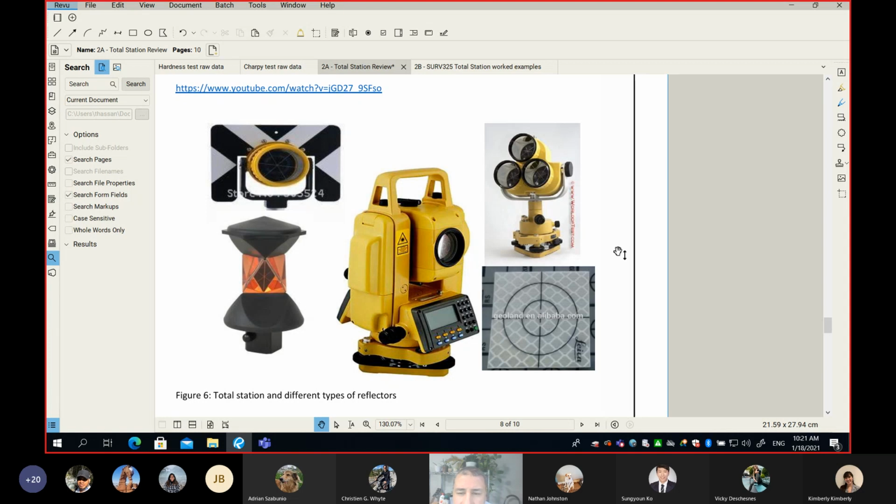Can I get some help, please? I'm asking you, do you think I'm going to, for example, I want to find the coordinates of a manhole or a building corner or any feature on site, let's say also a fire hydrant. Am I going to bring a tripod and set the tripod on top of the manhole and get this assembly, level it, center it above the point to get the XYZ? Or is that too much, that's overkill? Not likely, that's too much time, unless it's a long way away, or you're setting up a new benchmark maybe.